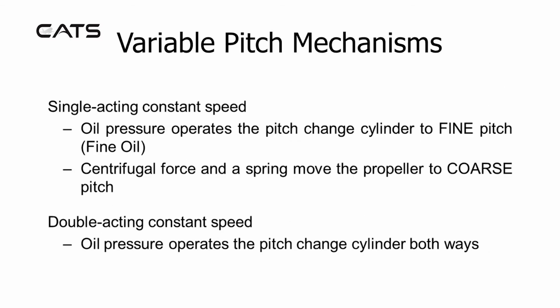Single acting constant speed. Oil pressure operates the pitch change cylinder to the fine pitch. Centrifugal force and a spring move the propeller to coarse pitch. In the double acting constant speed mechanism, oil pressure operates the pitch change cylinder both ways.